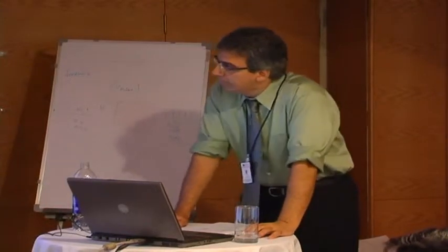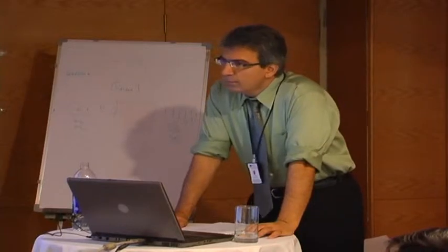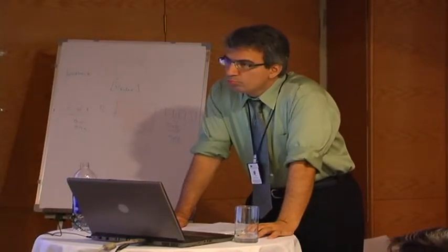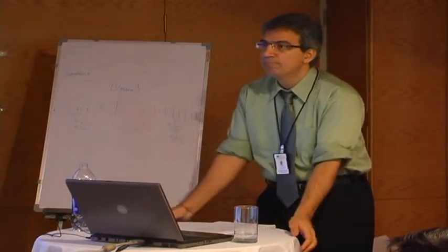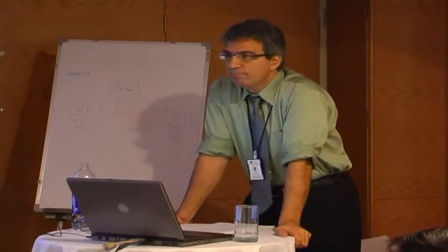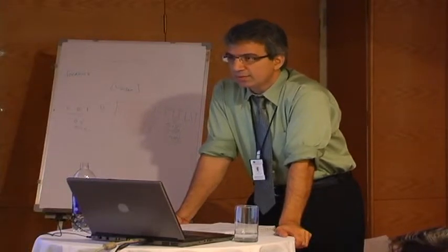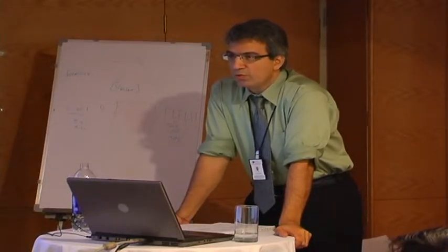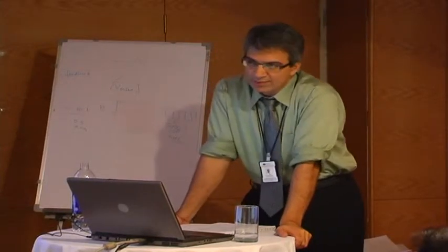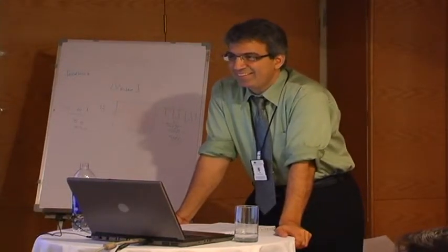No, I'm talking about only the dip portion. For a given motor, two kinds of motors with L equal to some L1 and L2, where L1 is greater than L2, the dip portion will be smaller for a motor with higher inductance. Maybe I can increase or decrease the switching frequency according to the motor inductance. So then I can see a smaller dip for the higher inductance motor if you change the frequency. Yes. If you go from 20 kilohertz to 1 kilohertz, I can see a smaller dip also.